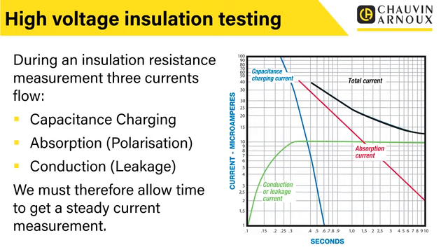But what you will see is that when we first apply the test voltage, we will get a current flow. And that current flow is going to effectively charge up that capacitor. So initially we'll get a current flow, but once that capacitance is charged up, then that current basically goes to 0, or certainly becomes negligible. So we have this charging current. You can see there the blue line when we first start off, probably for less than a second, we will see this charging current.